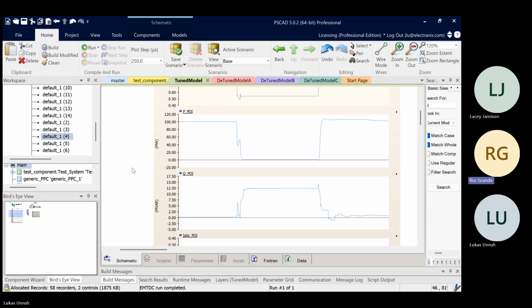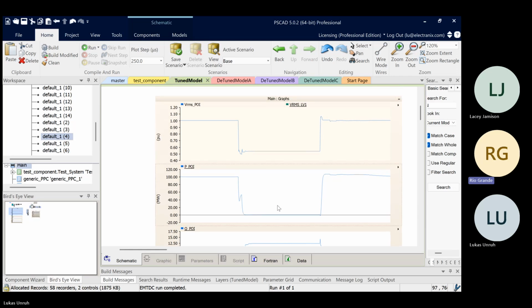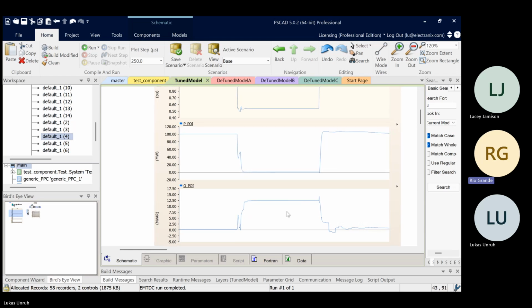I'd say some regions might have a requirement for what level of active power you maybe need to maintain during the fault. They might say, try to maintain your pre-fault active current or something like that. But in most scenarios, you should be trying to emphasize reactive power during the fault. There's some exceptions to that, but most of the time that's what we want to see.